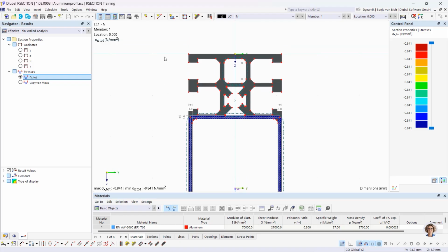If you drag a window from left to right, everything that's completely within the selection area will be selected. If you drag a window from right to left, everything that is intersected by the selection area will be selected.